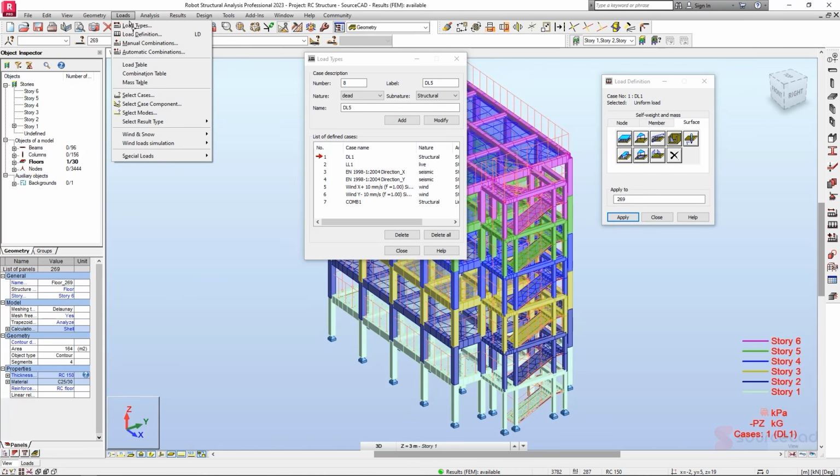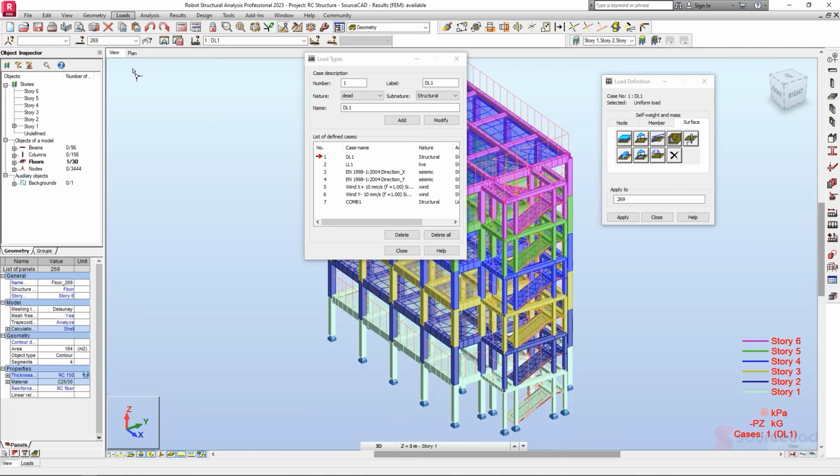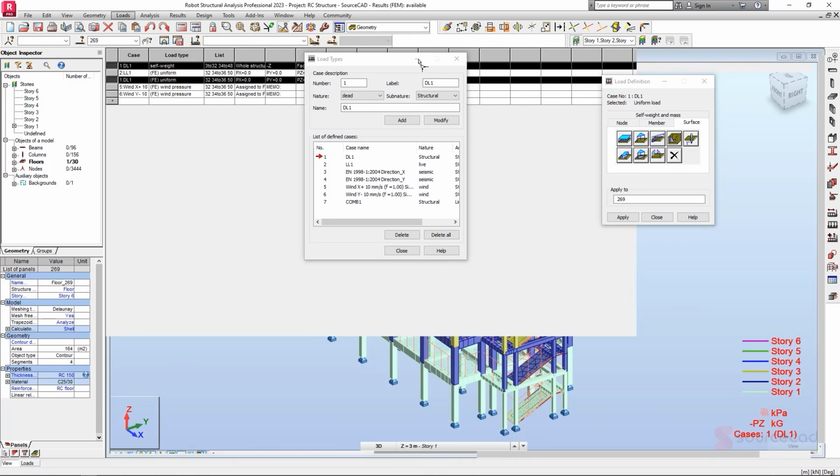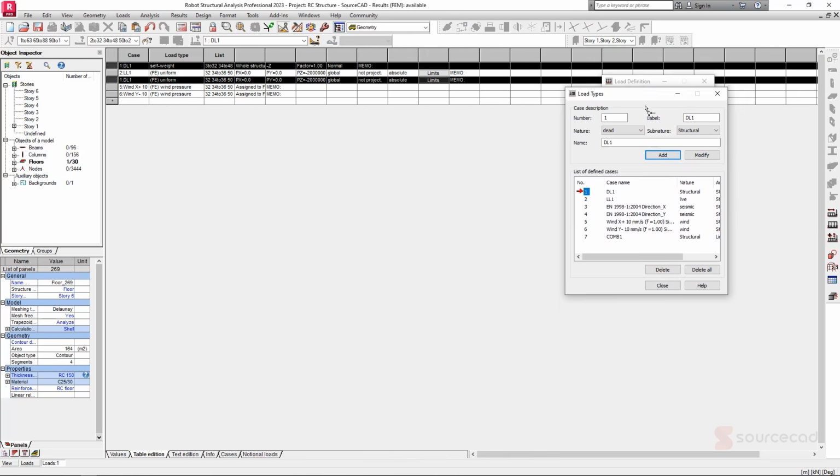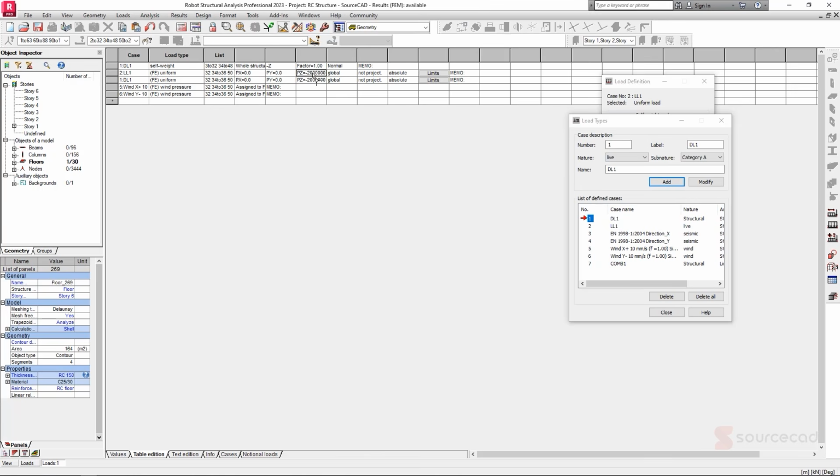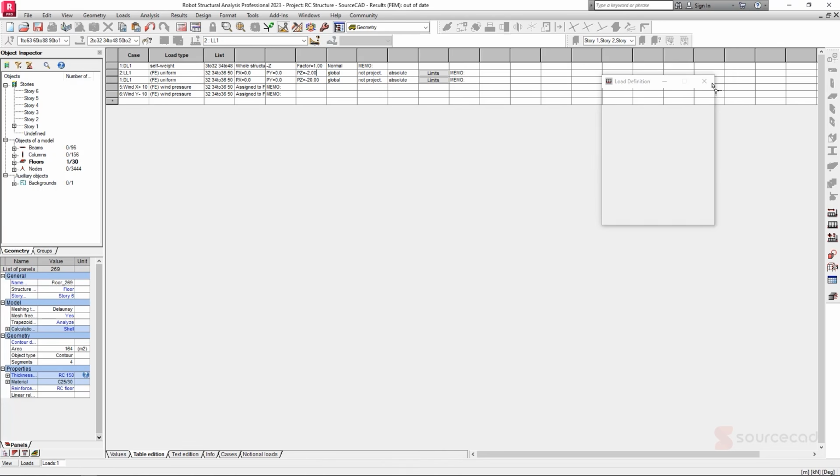So to do that is quite easy. Go to loads, then we're going to go to our load table. So click on this, and then we're going to change our value within our load table. So under our load table, let's update it accordingly. So this one, we can move it on the side. So for the live load, this will be -2 only, like so. For our dead load, it will be -20 only, like so. And just like that, now it will update accordingly within the structure.